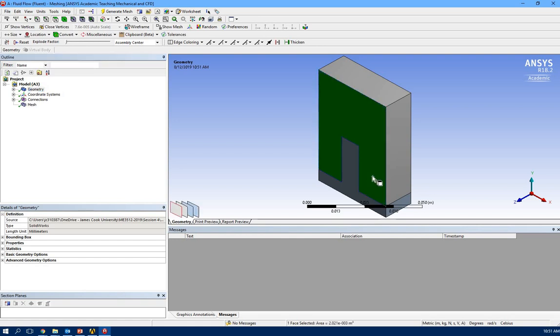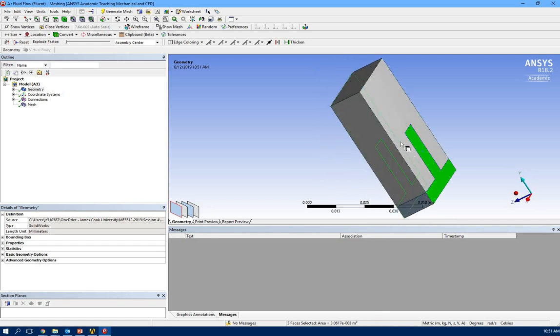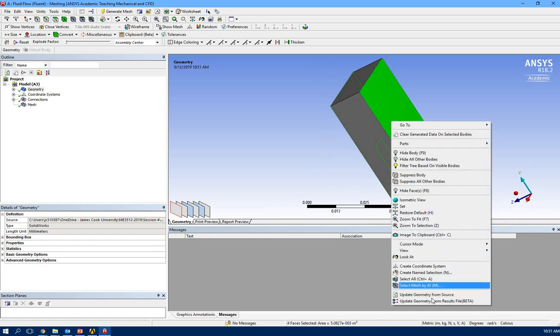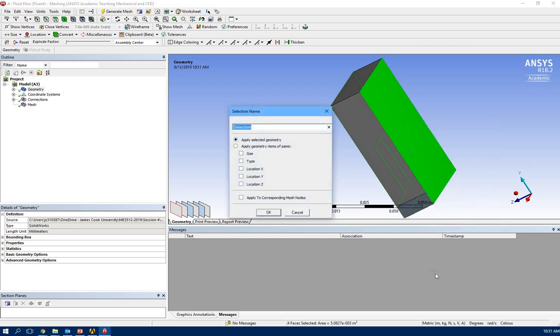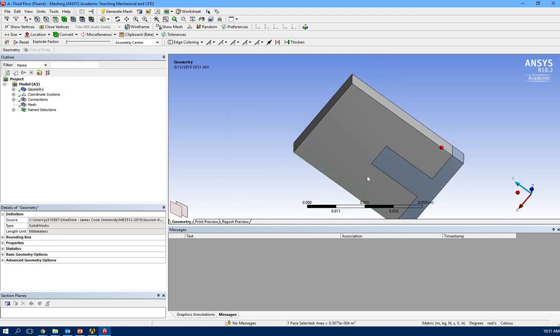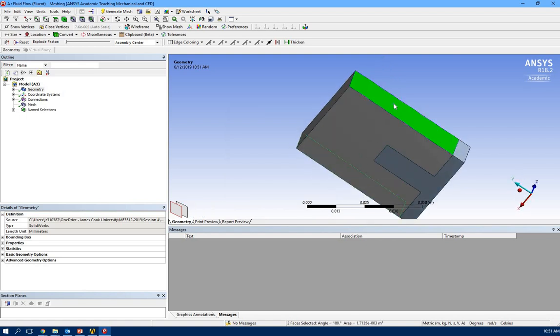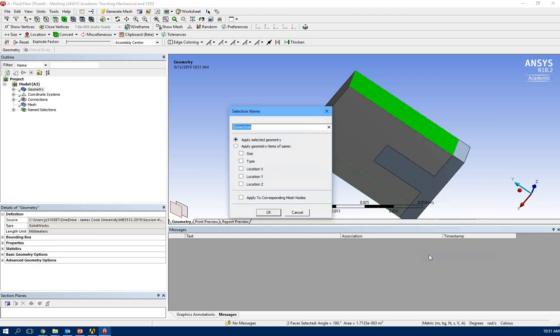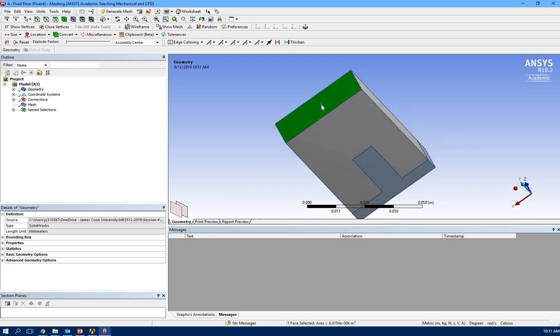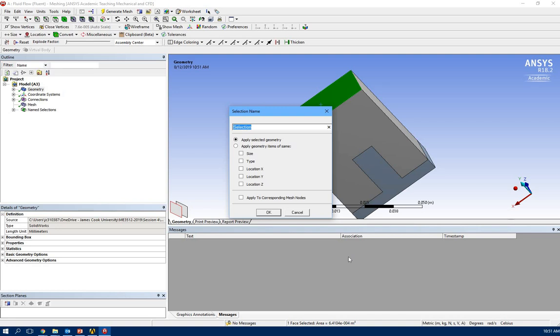As you remember from the previous homework, we decided to have these two sides as a wall. So where is name selection? So walls, and air is going to come from the left and right side. So let's name it inlet, and it's going out from the top because we have natural convection on air. When it heats up, outlet, it's going to move upward.